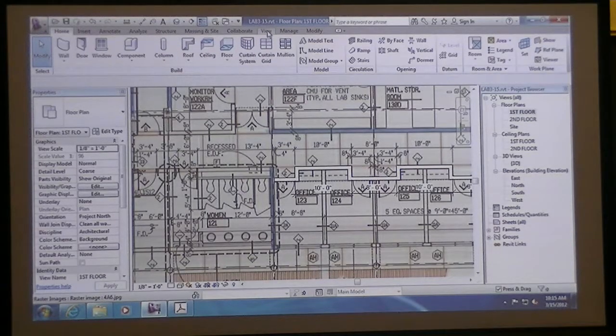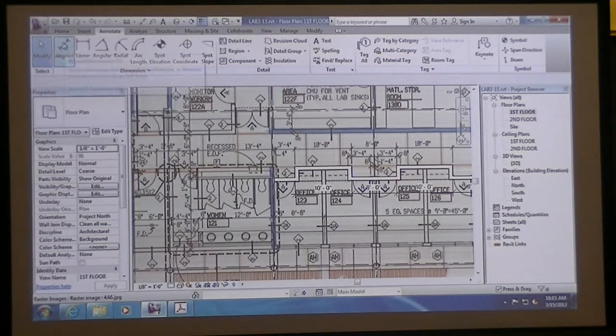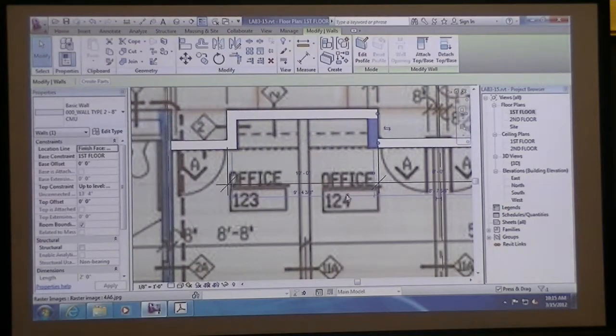I want to know about that align dimension thing, that when I'm taking the dimension, it's kind of taking the center line and not the edges. Oh, so you need to draw a real dimension line. Remember I drew it under Annotate and used Aligned Dimensions to make an actual dimension string. The one that you saw to your center lines is a temporary dimension. So when I click on it, you see I get another set that's going to the center line. Those are called temporary dimensions.